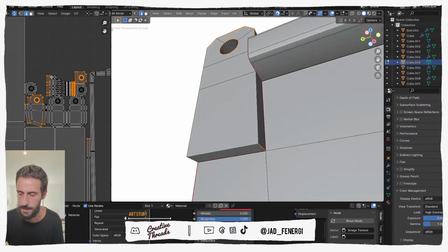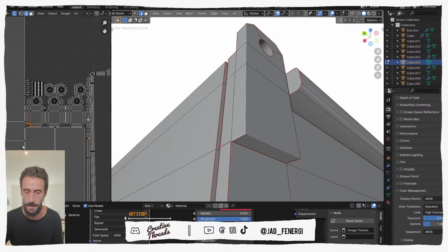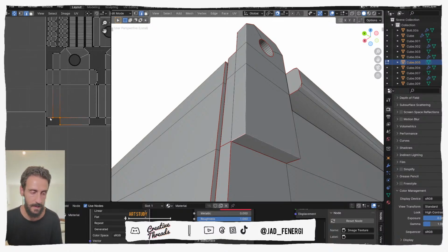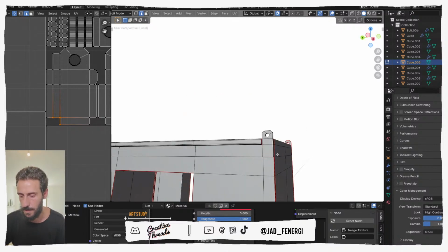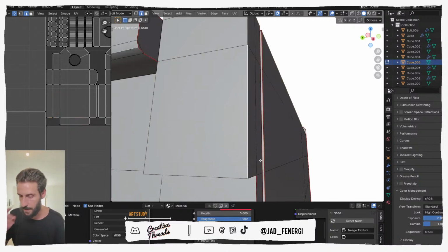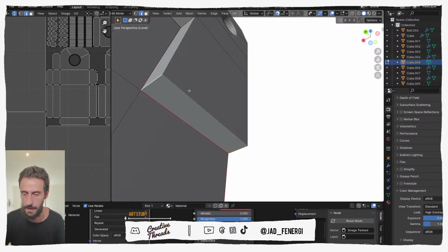It's not it. We still need to do one more cut, which is here. Yeah, it's working fine. So you can see before doing that cut, it was a bit messy in here. And let's do the last one. Just pick any edge, press period on the num lock. And now we just need to cut here.